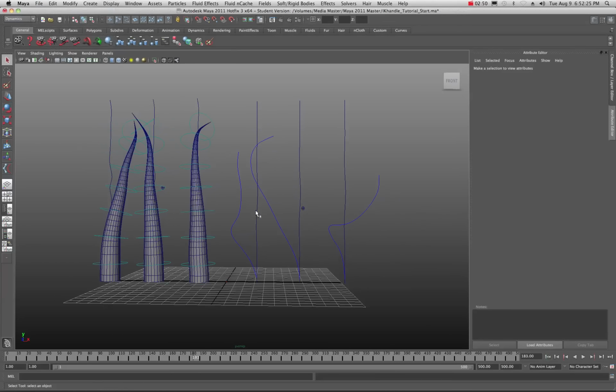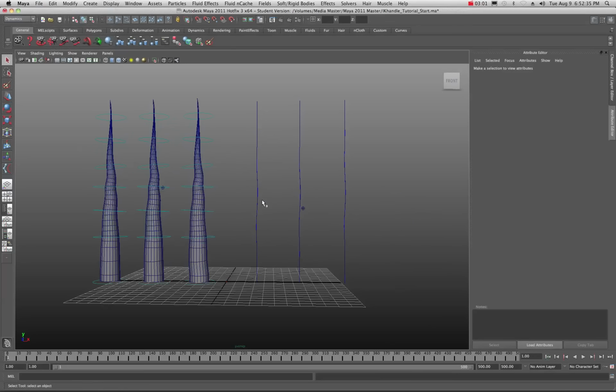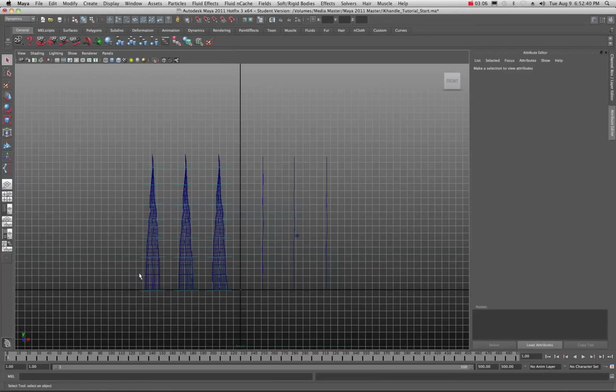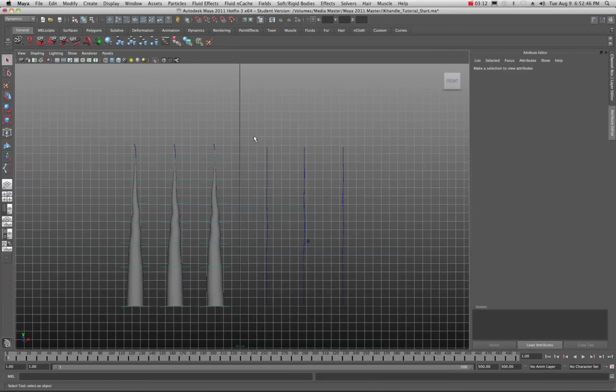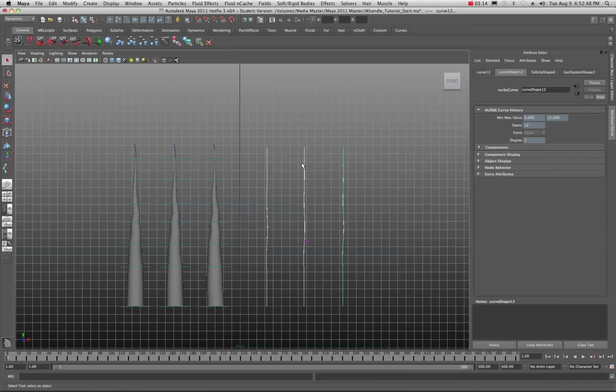So let's take a look at this geometry now. What we need to do is create some bones to go along here on these EP curves. The best way to do that is to reset, go to the beginning, press your space bar, come down here, press space bar again, and let's open up this front view. You can see my curves right here, those are the other curves.